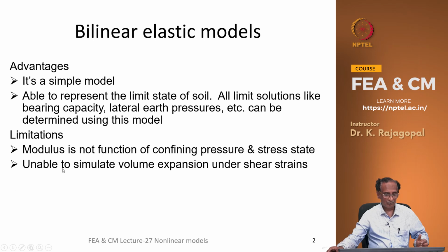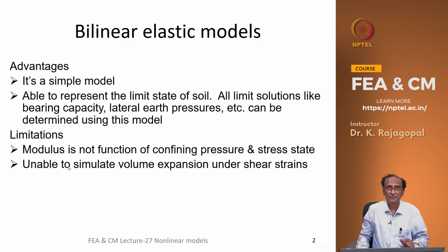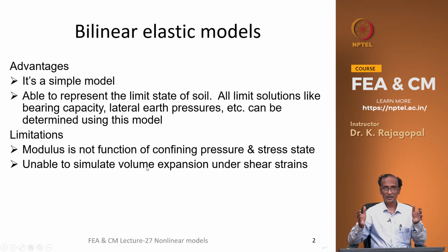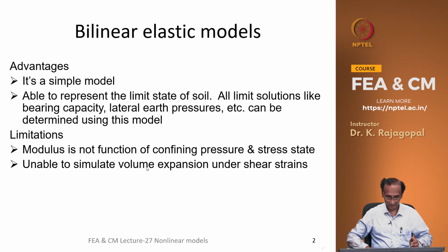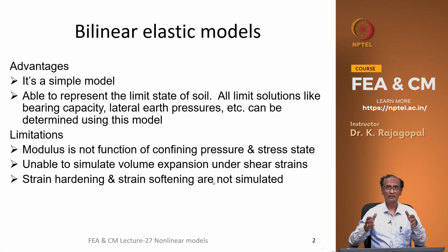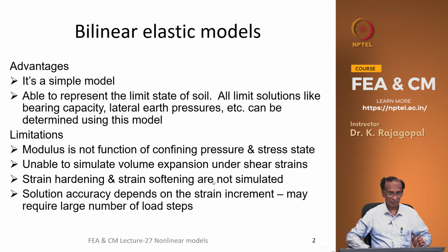And these models are unable to simulate volume expansion under the shear strains. That is another major feature of the soils, and that we will see later. And the strain hardening and strain softening are not simulated by these bilinear elastic models.